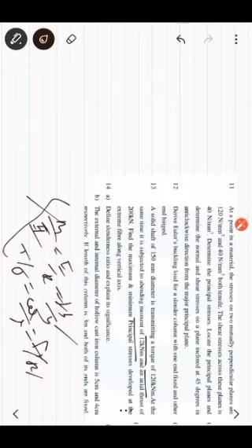They have given the torque, means torque is known. Then using the torque you have to find out the stress value. So torque T by J into R, you have to divide everything, and you have to get here sigma b by y, that you have to determine by using the moment in Newton meter, and the axial force, the thrust, is also given. So you can put three values: one is bending, another one is shear, another one is axial. So sigma 1, sigma 2, and tau. This problem I will definitely discuss after I give the derivation, that is from the third module.